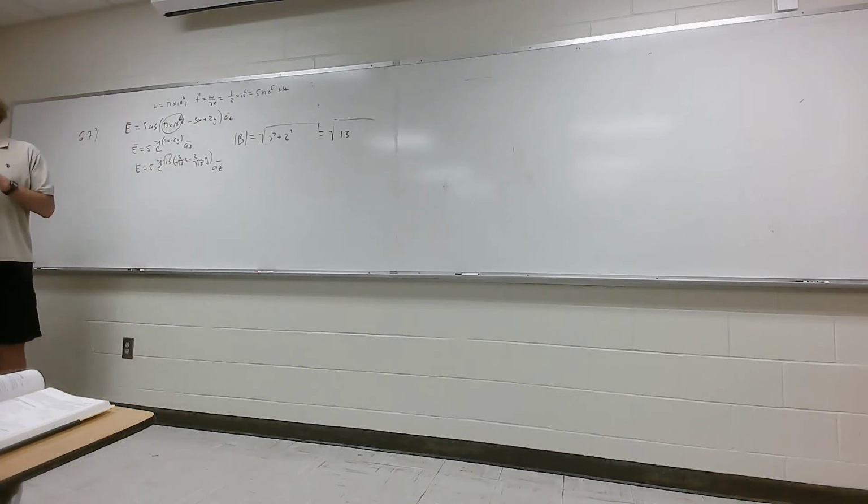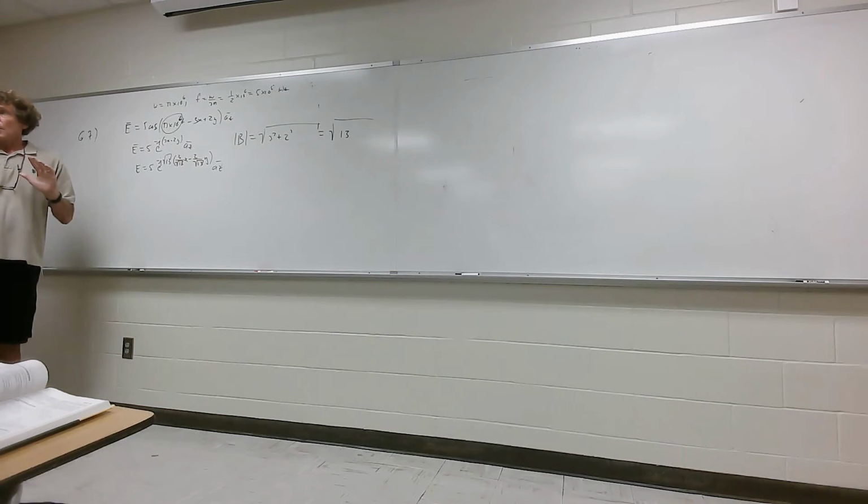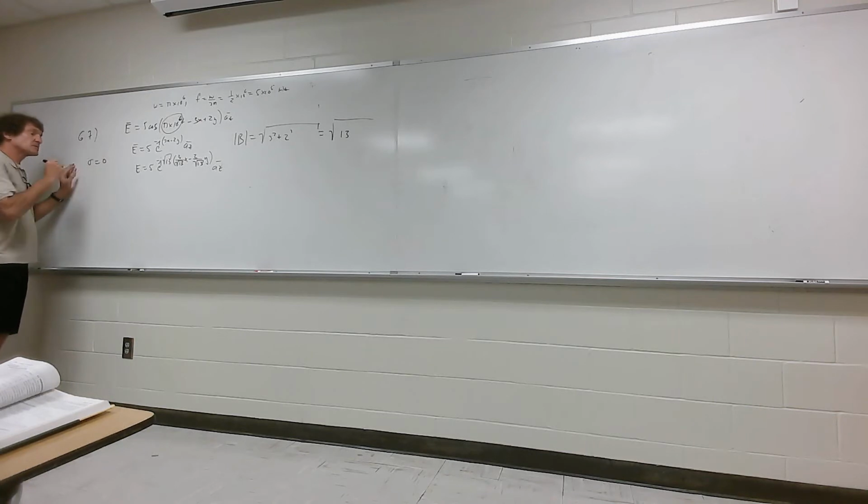Now, I'm moving a little quick because we did this last time. I wanted to get to where I was last time. Y'all remember this? Now, one of the things we can find out is what material we're in. Now, you didn't see any e to the minus alpha z. Y'all with me? That means it's lossless. That means you can state right away sigma is 0 for this one. Follow me on this, everyone?